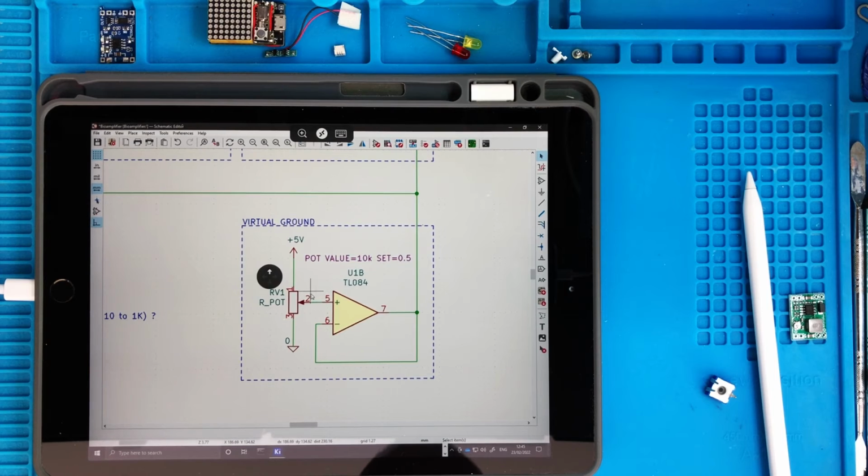So the purpose of this is to have 2.5 volts here as a reference. These are amplified by this amplifier in a so-called buffer configuration, which means that the gain of this thing is 1, and we can see this in better detail. And here what you have is again 2.5 volts, but now the current is amplified, and so this can be able to power up, let's say strongly, the rest of the circuits at 2.5 volts.